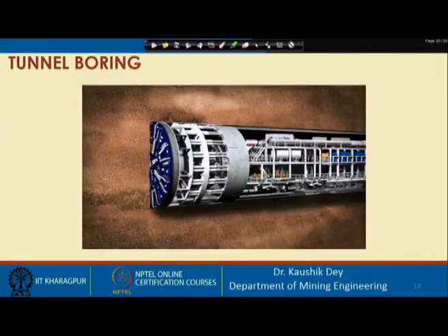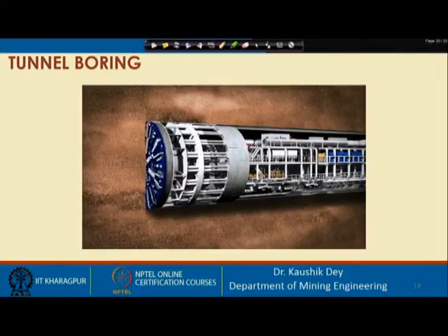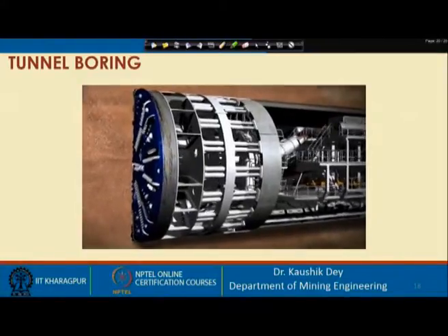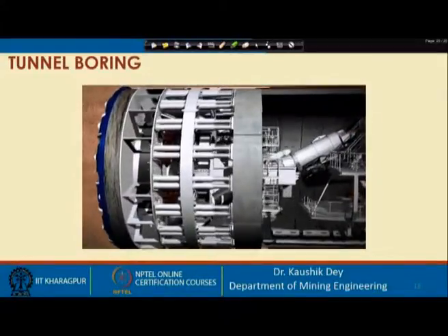As the cutter head is rotating, you can see the ground being cut. Depending on the geology below the buildings above, each TBM will travel between 90 and 150 meters each week, with the shields being forced against the ground and advanced to within a millimeter of where it needs to be.